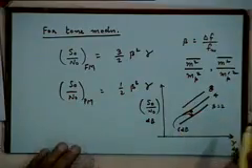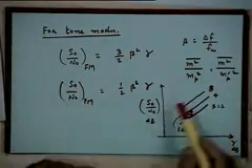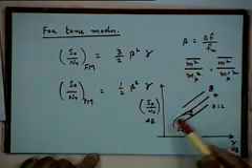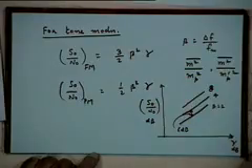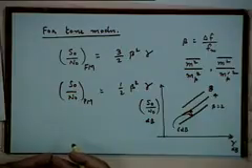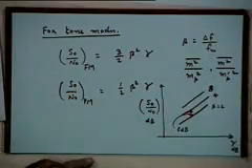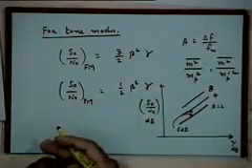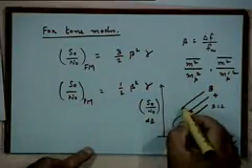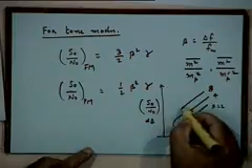But you will also have noticed a curious thing that I have done here. I have not taken the straight lines like that, and I think you can guess why. We discussed that this analysis has been carried out only for the small noise case, that is, when the input signal to noise ratio in the message bandwidth, the value of gamma, is sufficiently large. The moment you make it smaller and smaller, the analysis becomes invalid. So we simply can't say the straight line behavior will continue on this side. Actually, the straight line behavior ends somewhere here, like this.